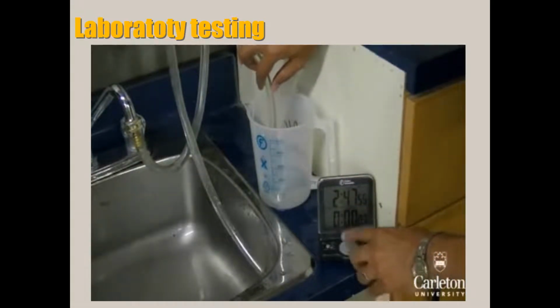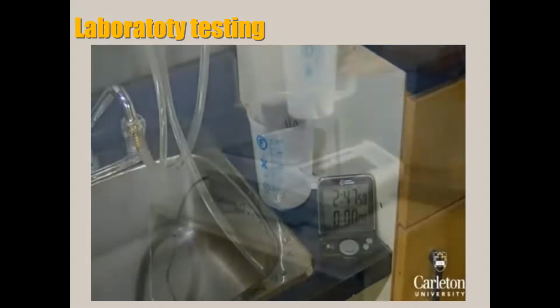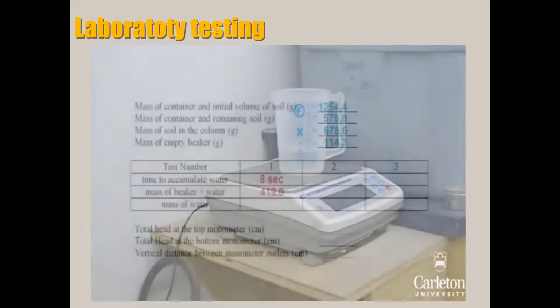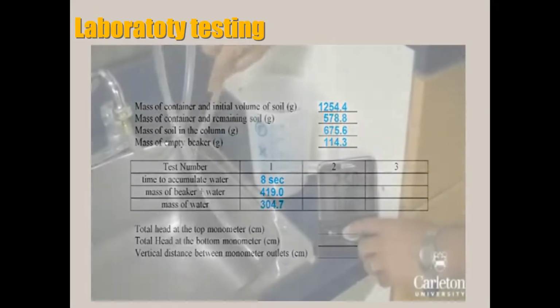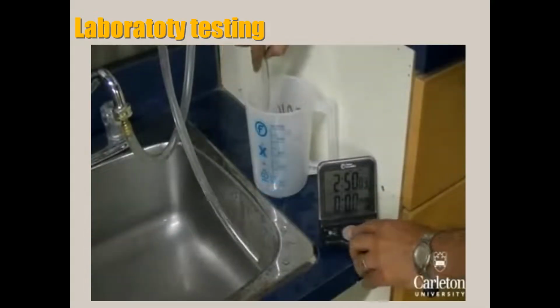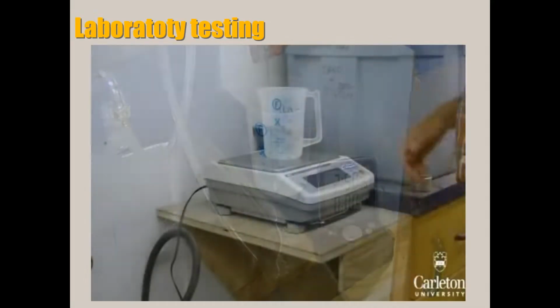Simultaneously stop the stopwatch and remove the discharge. Now record the mass of the water plus the beaker, as well as the time it took to fill, in seconds. Empty the water and zero the stopwatch to reset. Repeat this test 2 more times, each time aiming for a different amount of water.